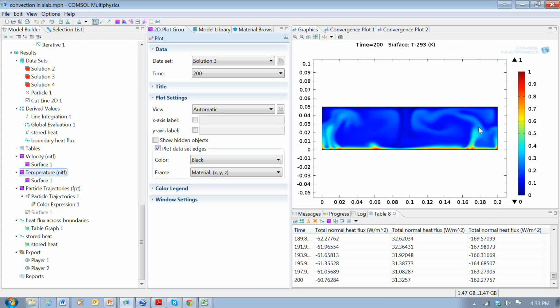But if you can cut off and prevent this free convection cell from forming, then air actually is a pretty good insulator. And so what's done then is to put in material that is very low density and has a lot of air trapped in it, but the air is in some small cells, like little cells in styrofoam, or in between the pieces of fiberglass.